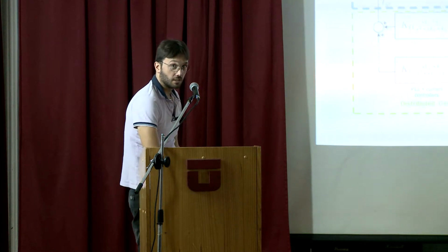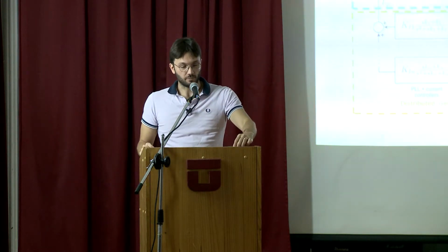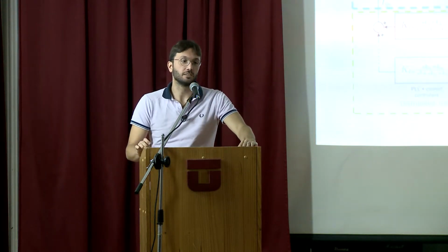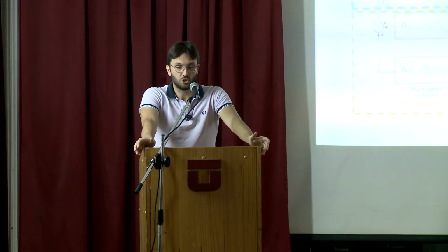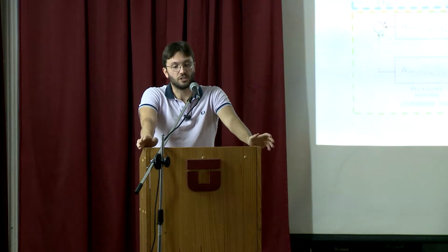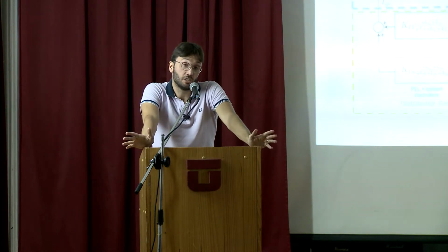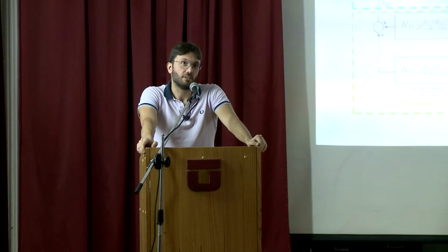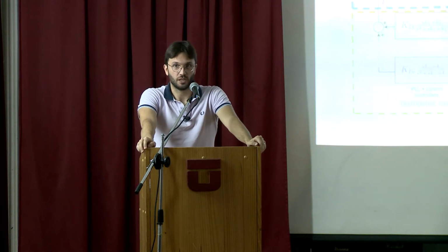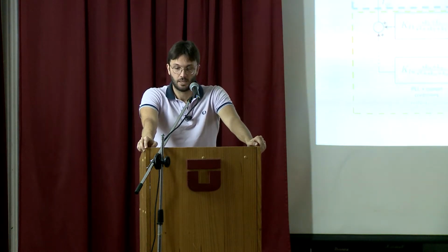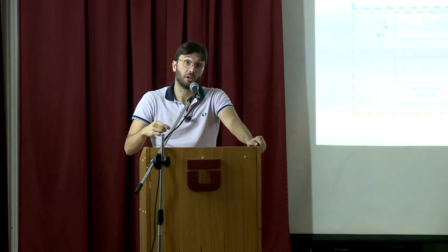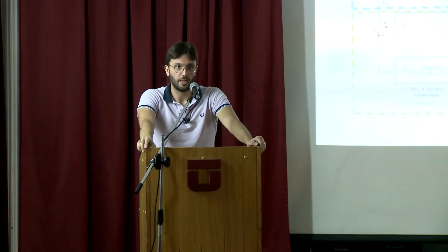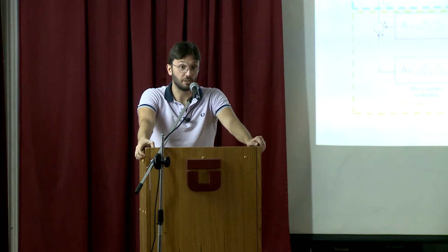So, where is the trick? Can this work? Well, when you try to implement, at the beginning it didn't work. Because in this interaction, the two systems have no communication. But they have a PLL, meaning the distributed generation has a PLL. So it means that there is a delay between the moment where I increase the frequency and the moment where the distributed generation is actually limiting the power.